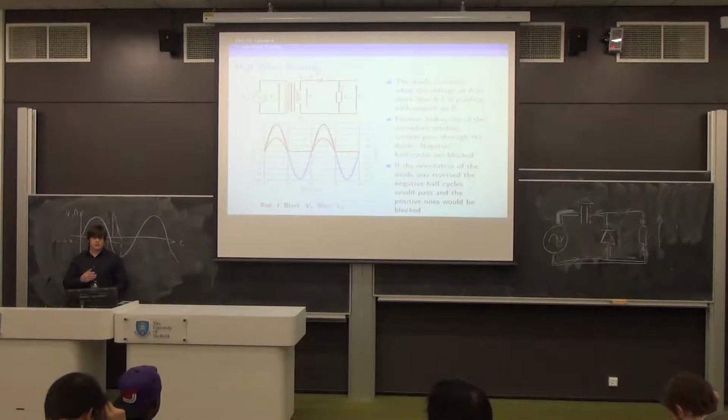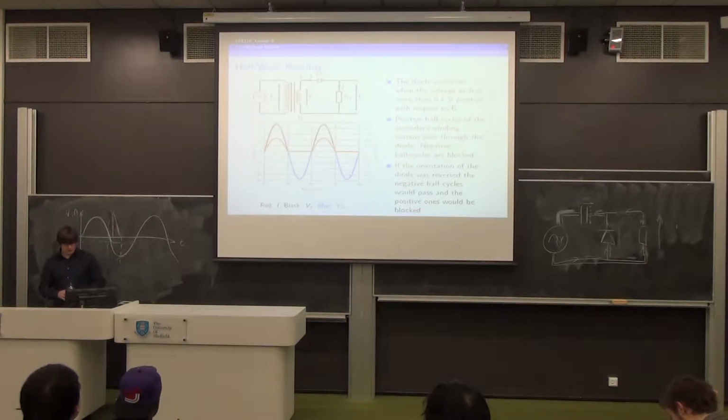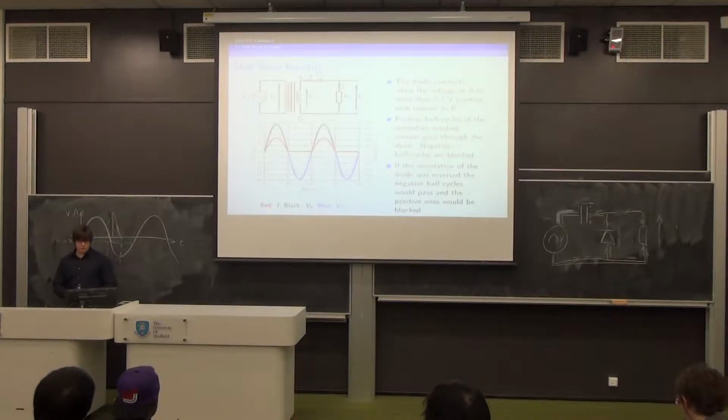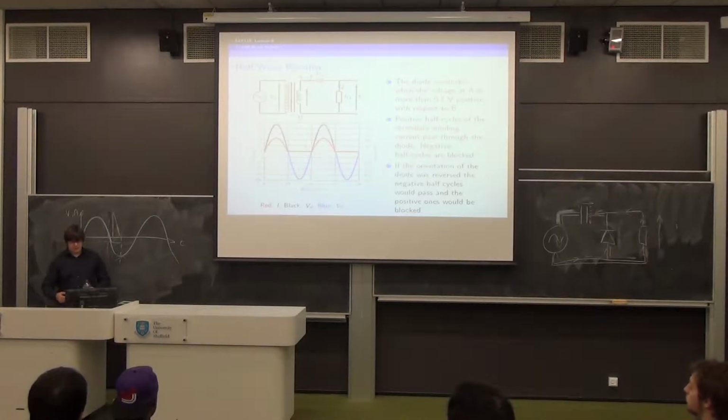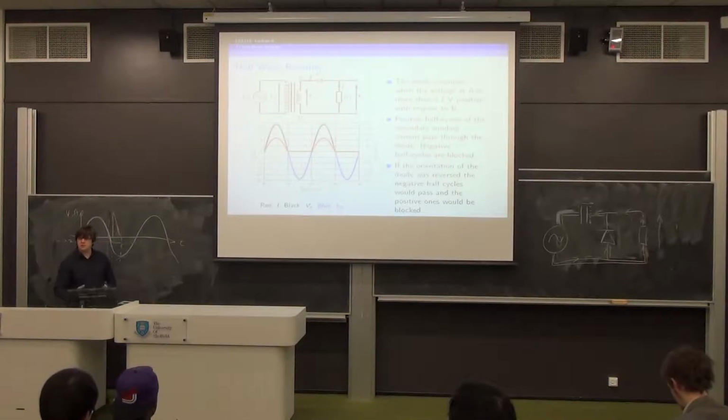The second half cycle, and the fourth half cycle, and so on, don't get a look in. So the current actually only flows for half the time. So if you were driving a machine off this and it was DC, you'd get torque, no torque, torque, no torque, and so on. So it's rhythmic, which is what sets up the oscillations, and you don't actually extract very much power.